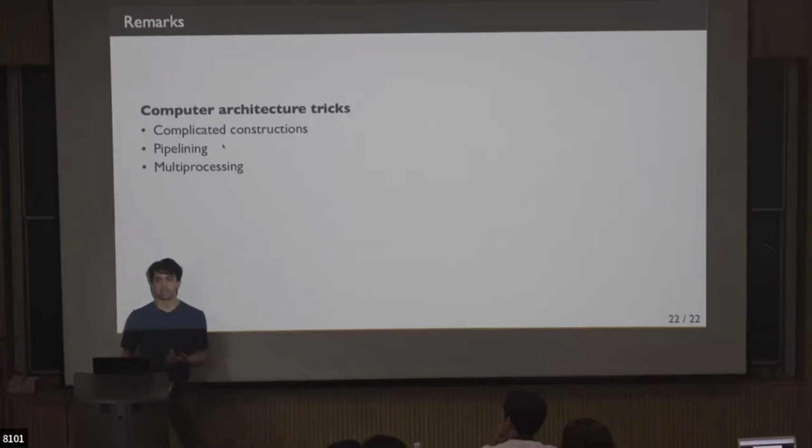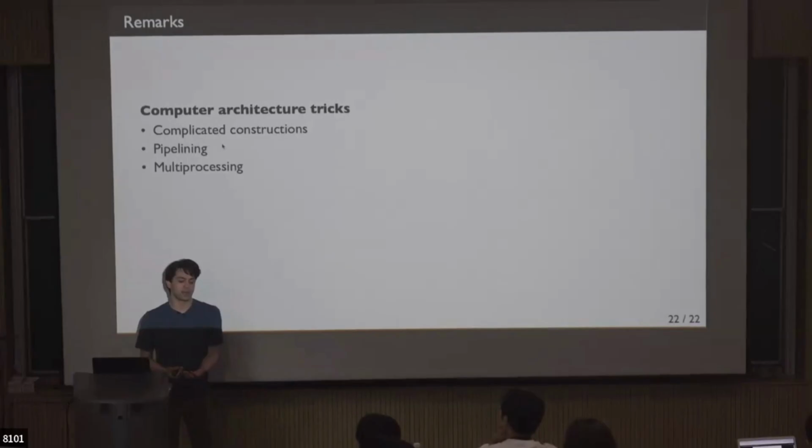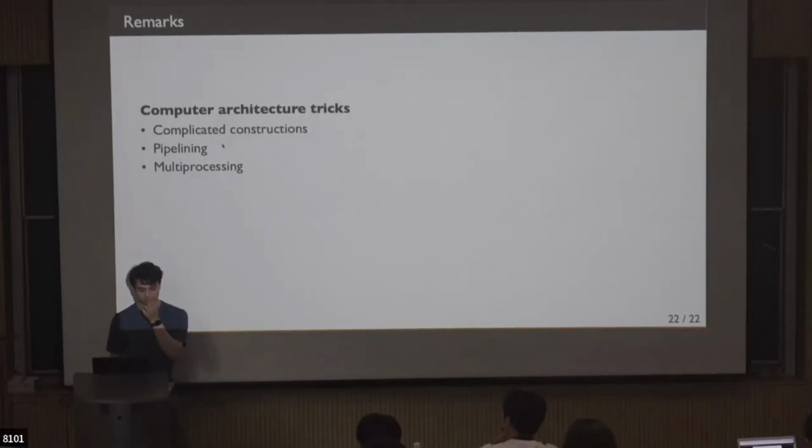Instead of applying an AND gate to the first 2 bits of some register, they might take this 512-bit register, chunked up into 32-bit floating point numbers, take a second one, and add them all. A single instruction might specify a large number of floating point multiplies, which is a very big circuit to be running, and it's described using a very short instruction. So we can do something very similar, you might imagine.